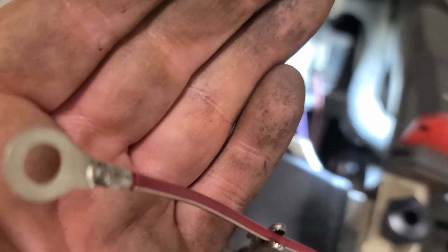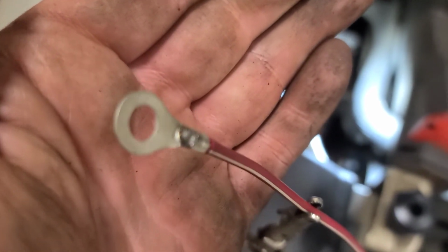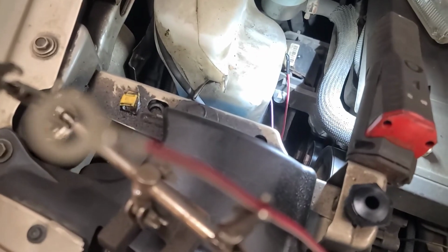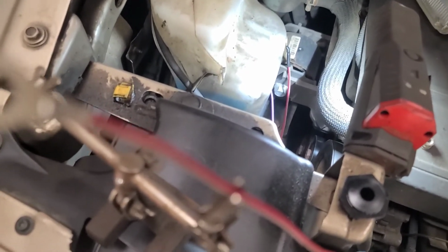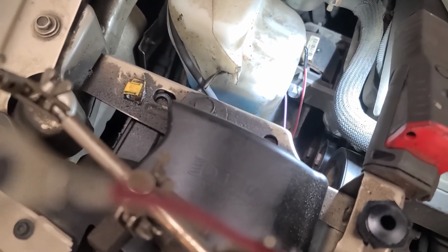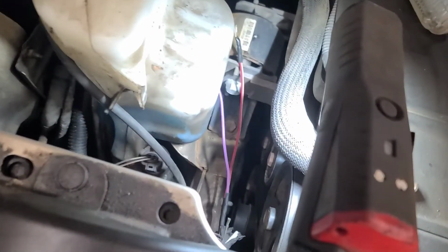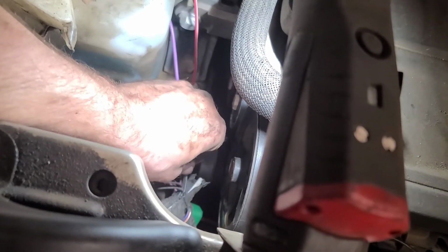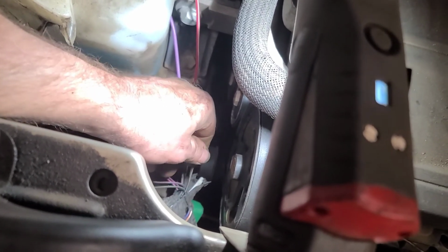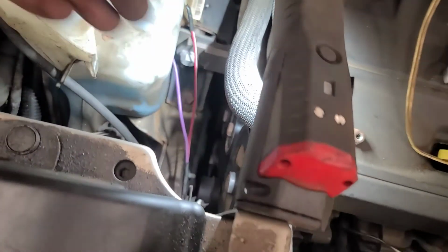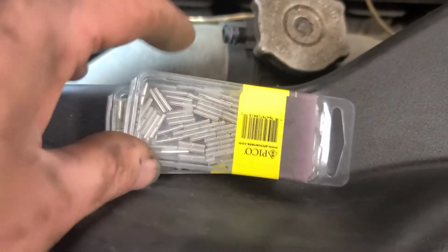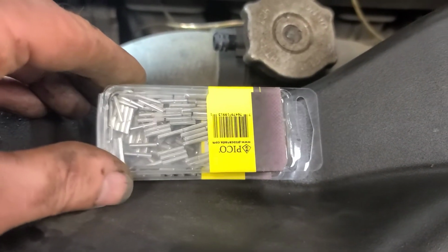Oh well. So if you solder the terminal, it will seal it to keep the salt from wicking its way up there. And we're going to put a piece of heat shrink over it as well. The other end, where we're putting uninsulated butt connectors in, the wires are compromised, and I'm not going to peel back 2 feet of harness here to attach a wire, so I'm using mechanical crimp and heat shrink.